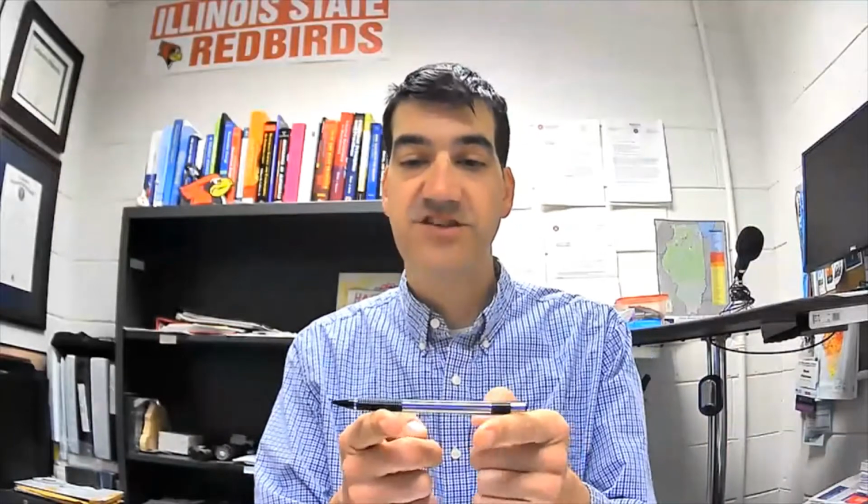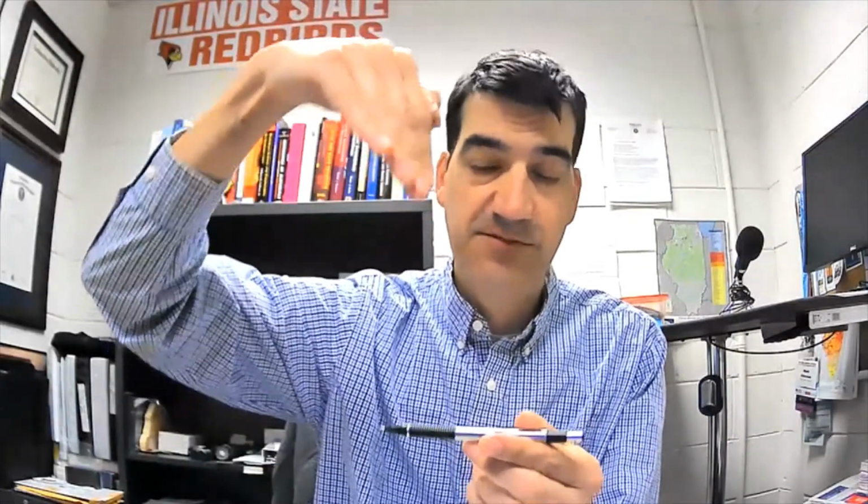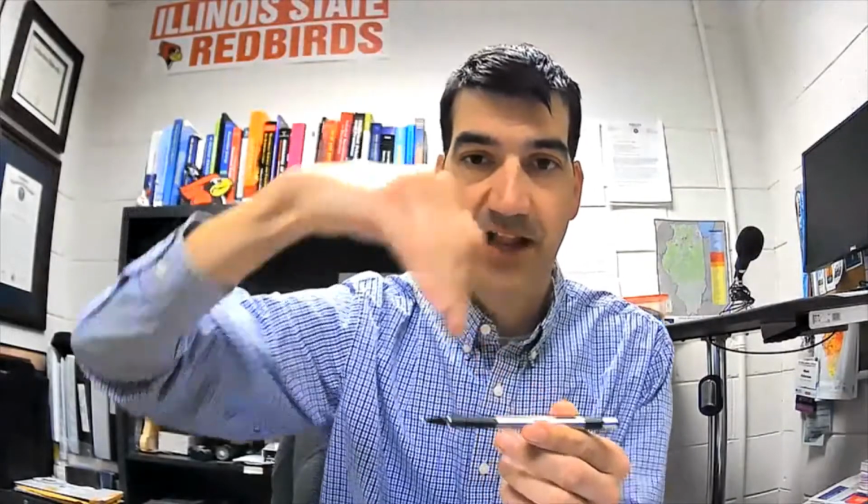But the way we're going to test your beams in Lab 8 is it's going to be a simply supported test fixture. That means it's just going to be resting on the test fixture, kind of like this, where you've got a support on the left, a support on the right, and then there's going to be a force from the Instron machine that comes down in the middle, right like that. So these supports are 18 inches across. The span of the beam in Lab 8 is going to be 18 inches.